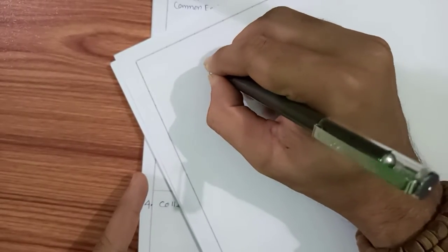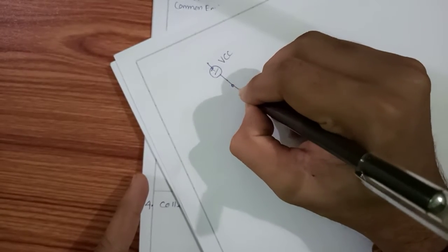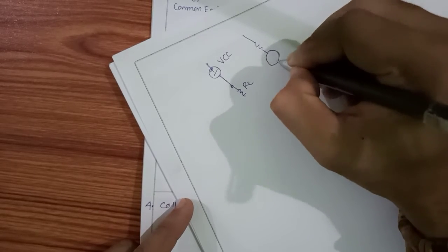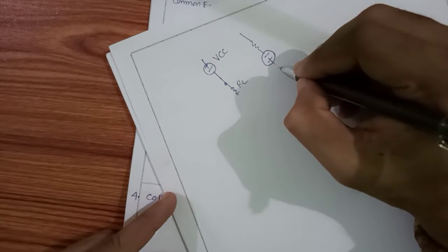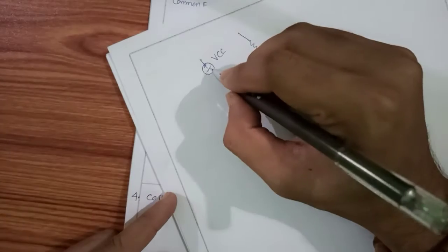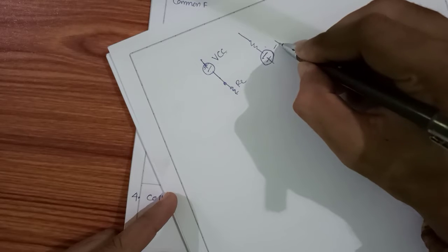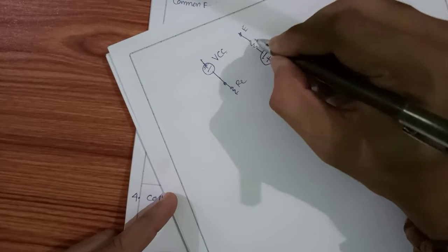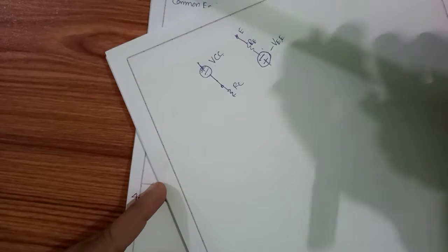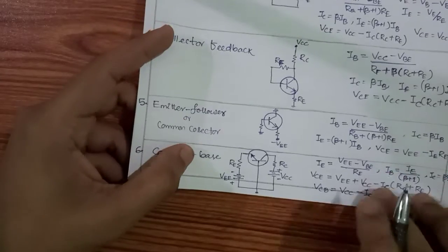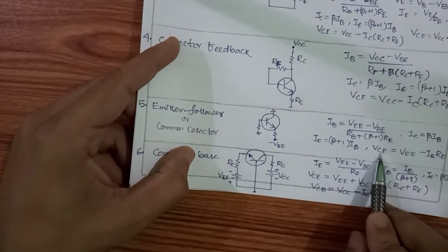Whenever we connect a voltage source, we connect it like this, positive negative, that means it is VCC, connected to the collector terminal, the collector resistor RC. As it is connected after the emitter terminal, how will we connect it? We connect it negative positive, and since we are moving in this way, we see positive to negative, so we write minus VE, because this is the emitter side, and this is RE. That's why the negative symbol minus VE, because it is connected in such a way that the negative terminal of the battery is connected to RE. So here we will find IB, then IC, then VCE.